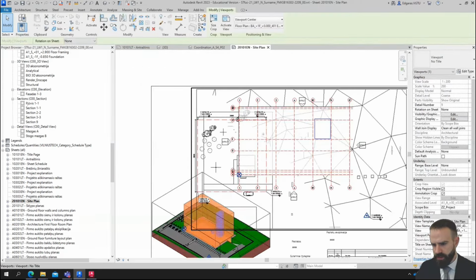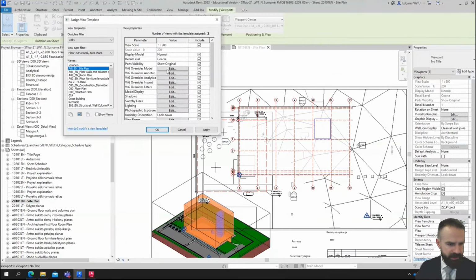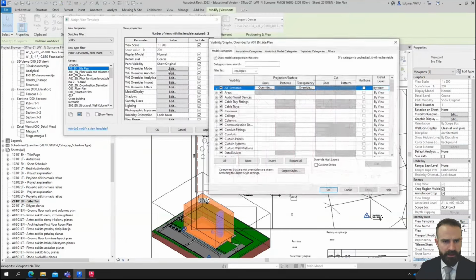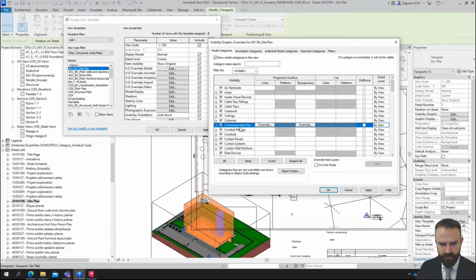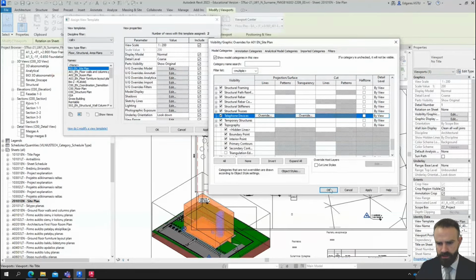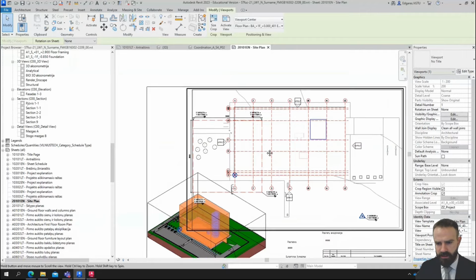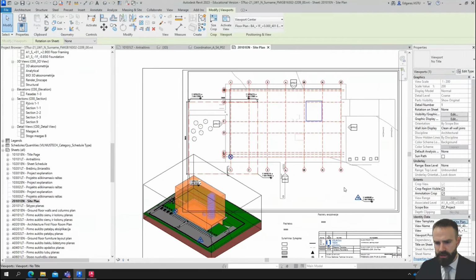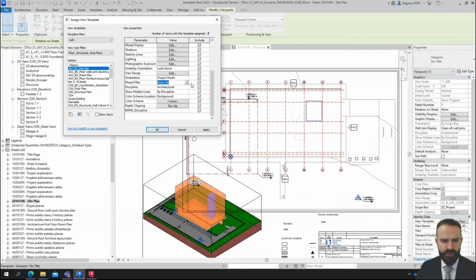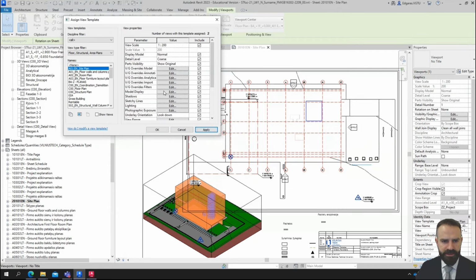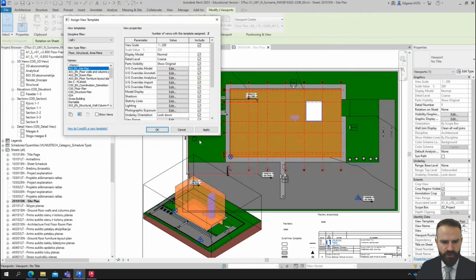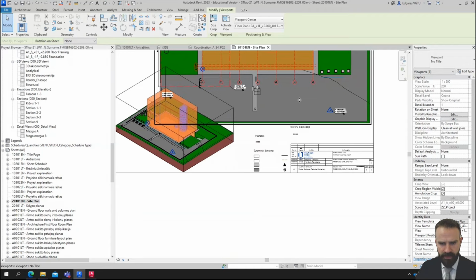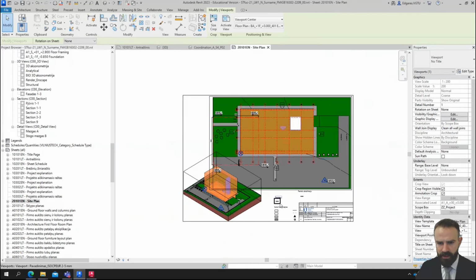Okay, so for the main drawing, I also modify site plan settings. I just go to edit model, remove imported objects, go to topography, turn off triangulation and click OK, apply, and I have a nice clean view. And for additional modifications, I should turn off the phase filter, just turn off non-phase filters. And for model display, I would like to see a colored model. Visually, it's more attractive and I can see more details.